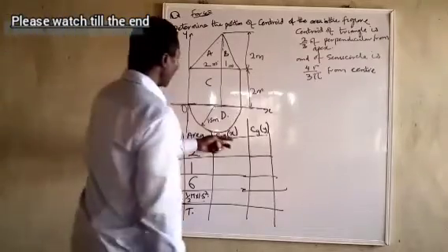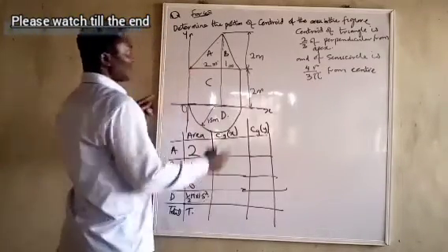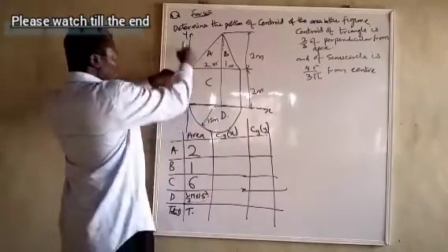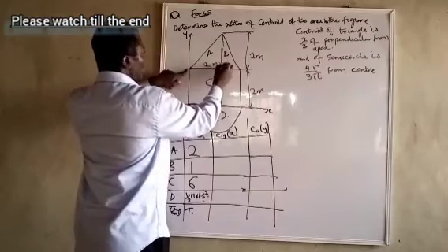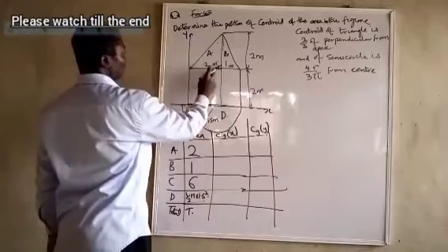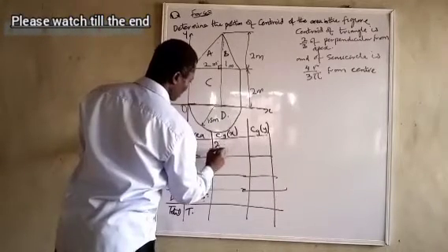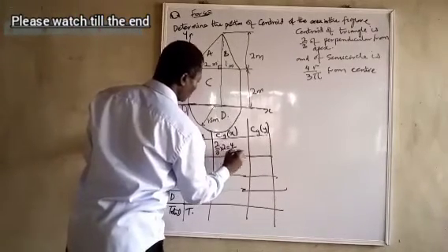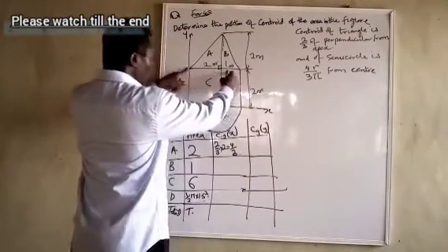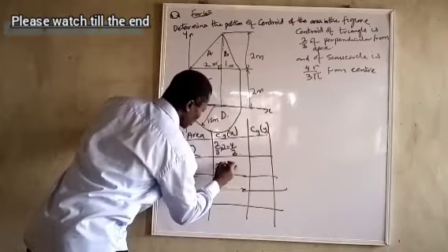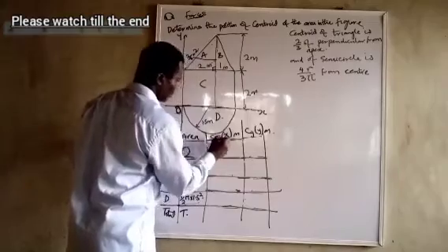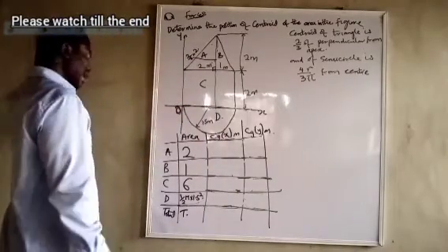Now, what is the center of gravity for this one from y? We have seen that it is 2/3 of the perpendicular from the apex. So this will be our apex since we are taking it from this place to this base. Because if you do it otherwise, it will scatter your calculation. So we have 2/3 times 2, which is 4/3. For this one B, it is going to be 2/3 times 1 plus 2. So you have 2 plus 2/3. Now, let us find the distance of the CG for each axis. We are taking the moment about the axis.